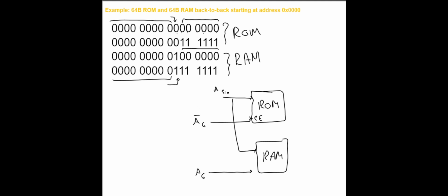Okay, we can clean it up just a little bit. So this will be my A6 through an inverter. We'll go here. Then if it's 1, it goes there. And we said that sometimes those chip enables are actually active low, so I need to integrate that. You can put a bubble, bubble. Then also put an inverter here, and put another, like, double inverters here, which is really like this.